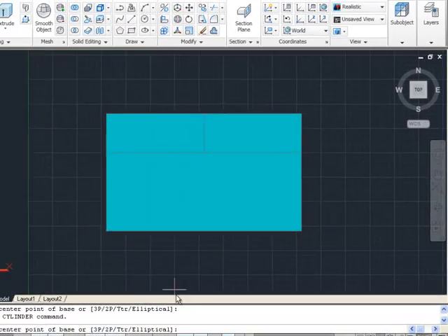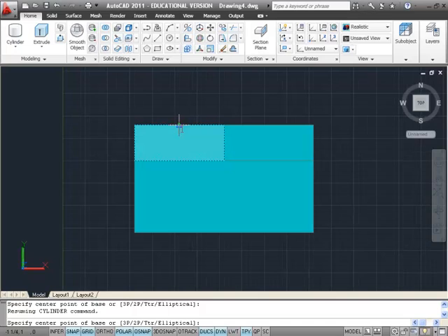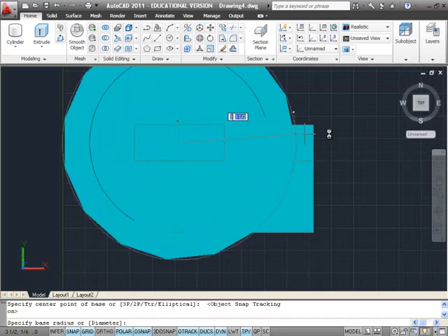and I'm going to hover over the midpoint, and what I want to see here is some tracking as I move my cursor, my crosshair from this midpoint. So I'm going to turn on the O-track option, and now after I hover over the midpoint it should give me some dimensions, and my dimension from that midpoint should be a ½ inch down, so I can use that as the center point for my cylinder.